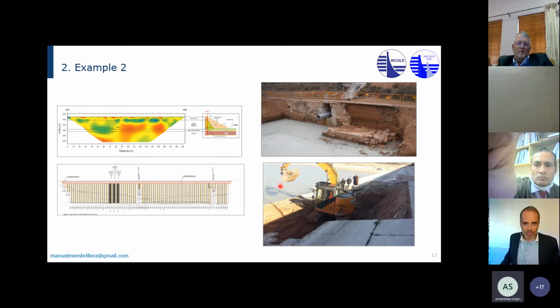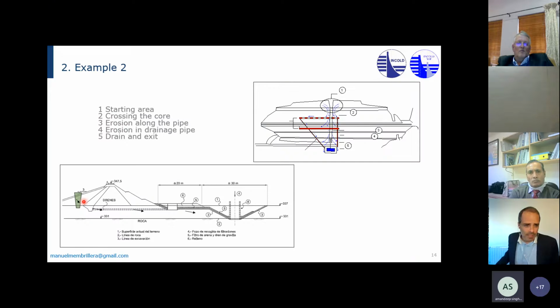So when we lowered the reservoir, this is what we found upstream, this huge sinkhole. And then downstream of the dam, we also cleared it up and we found this. This is the galleries I told you about, so water was flowing in this context. And this is what we've done to solve it. Essentially, we've created an inverted filter down here, downstream of the dam, and a way to filter and collect all the seepage and really stop the internal erosion from happening.